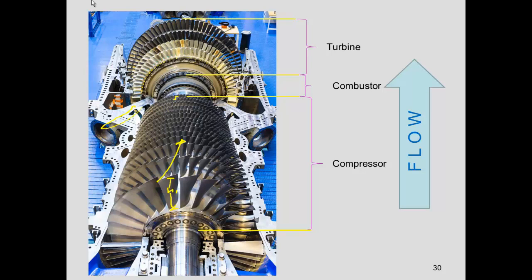Okay, so we're going to analyze this cycle, and since this cycle is, as we mentioned, composed of 4 processes that involve mass flow through the boundaries, we cannot invoke the first law for closed systems. We should invoke the first law for open systems.